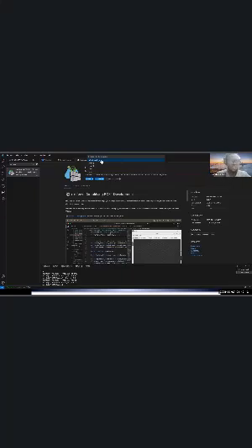So let me give some little history. Why do we have ROS2? The first ROS we ever used was ROS1. A lot of it was nice, but with feedback from the community, the Open Robotics team developed ROS2. I think there's Noetic. So now we have Humble. There's Jazzy, the most recent one, but Kilted is the most updated one that's undergoing testing. So I recommend anyone going into ROS use Humble. Humble is very stable. You have few errors when you use Humble.